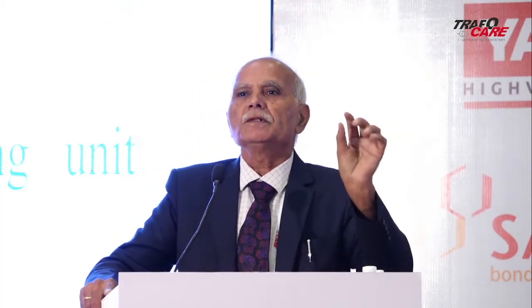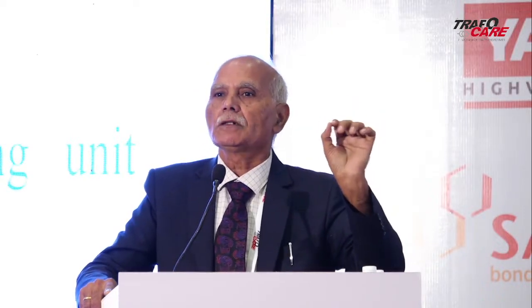All these aspects we are looking at in a very different way, because in USA, in the year something like 1994, they started assessing the solid insulation condition in a different way. And almost in the year 2000, we started this testing in CPRI for condition assessment of the solid insulation. And the solid insulation is majorly the electrical insulating paper, and this paper is made up of cellulosic material, which is a natural polymer.